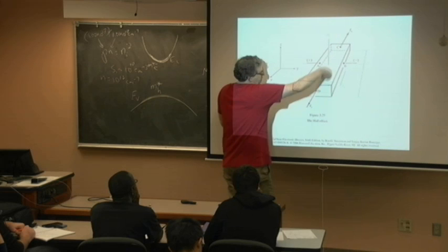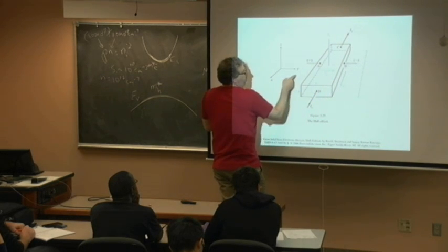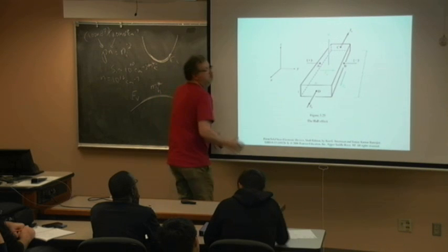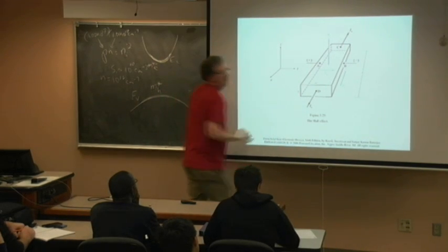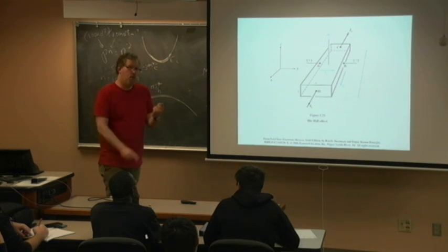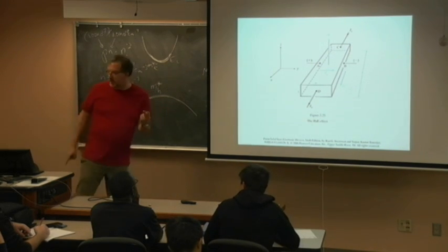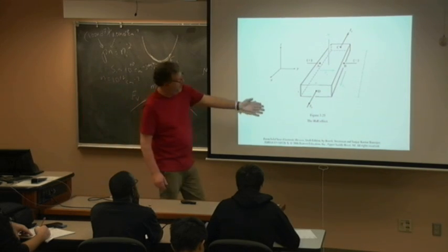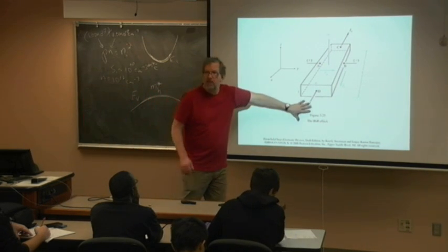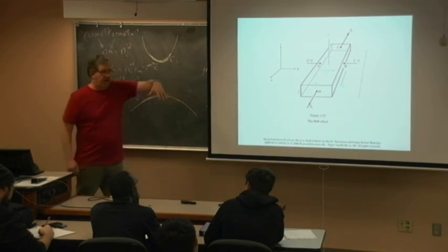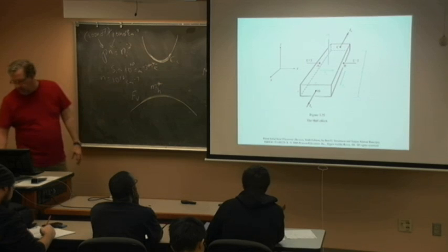So then the carriers are turning and they're coming towards the one electrode, and I measure a deflection, and I can measure a few millivolts. Based upon that, trust me, I can calculate mobility, and I can calculate carrier concentration to quite high degrees. So the Hall effect is very powerful. Usually, anytime someone has an epitaxial reactor, they usually have a Hall effect test setup right next to it, nearby in the lab.